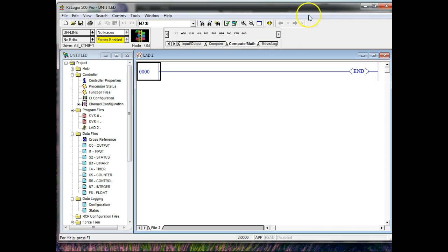Here's all our move and our logic instructions. So this does a move. It does a move with mask. It does an AND, OR, a NOR, NOT, and it does a clear. These are our file control and miscellaneous instructions where we can play around with fields and stuff like that. Shifts, program controls. You can see the list just keeps going on.